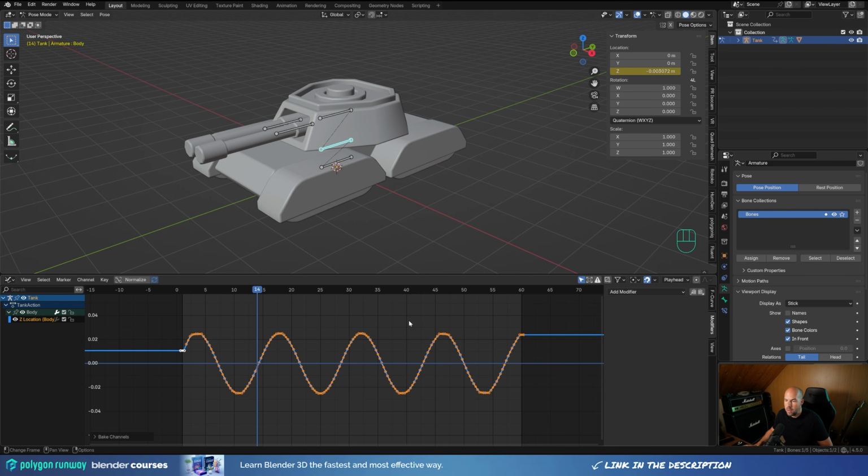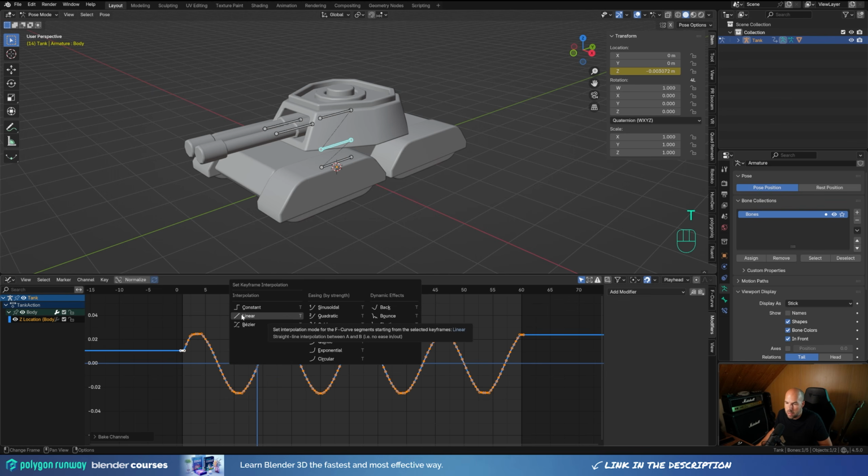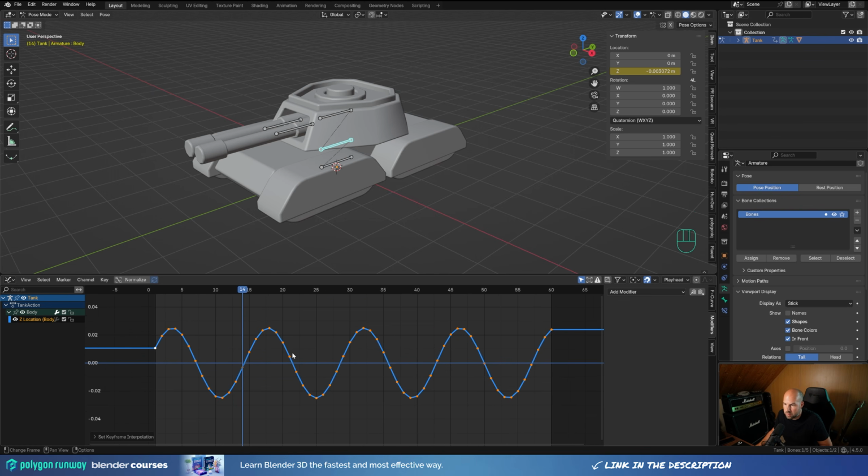Let's click it. That will basically translate this procedural animation to a keyframe on every single frame, because your engine probably wouldn't be able to recognize your procedural animation from Blender. So this is what you need to do. And now to simplify things, let's press T and change the keyframe to linear interpolation, so we don't need those handles since we got keyframes on every single frame.